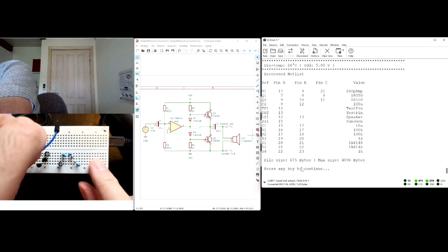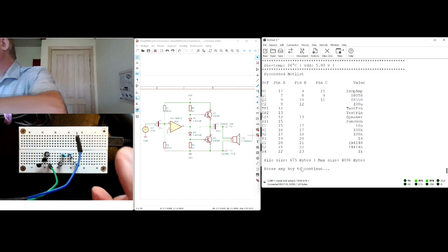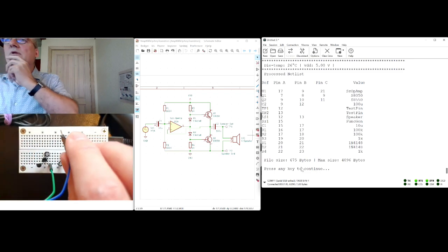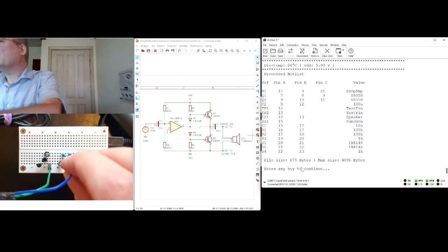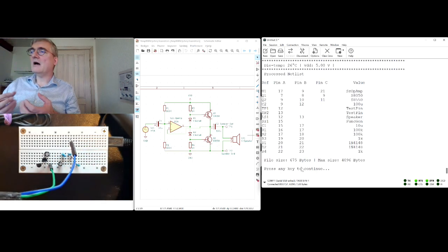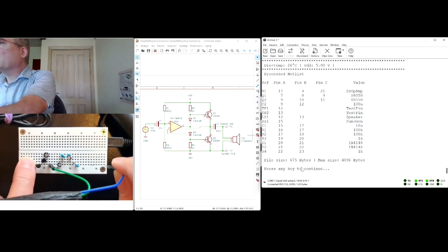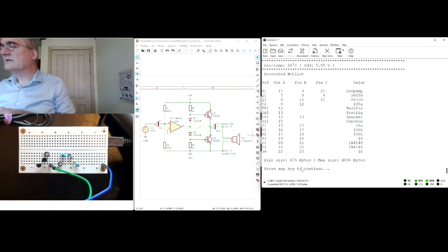And we'll take 12 here, somewhere, that's of course right here at the capacitor. And then we could put the other wire into number 13. That's a ground, but as this is with quite high power, I will prefer to put it into the common ground that we have down here. Now it's mounted.